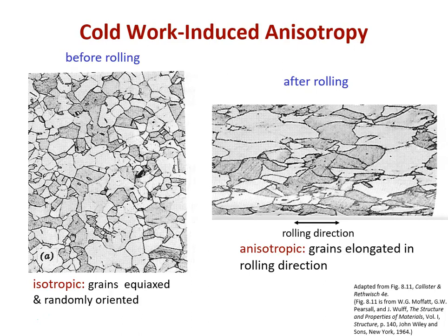So if we apply shear stress left to right, the dislocations in each of those grains that are on slip systems oriented to take advantage of that are going to move first. If we were pulling it in uniaxial tension, we would have obviously our highest shear stress in a diagonal across the material.